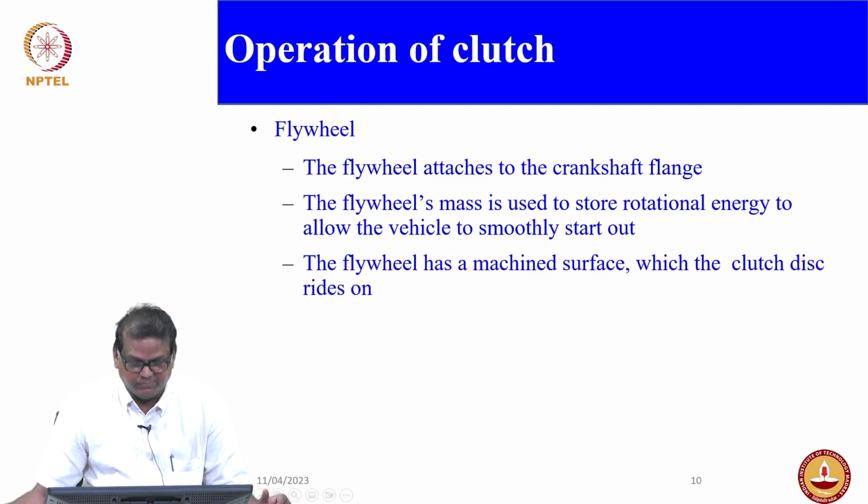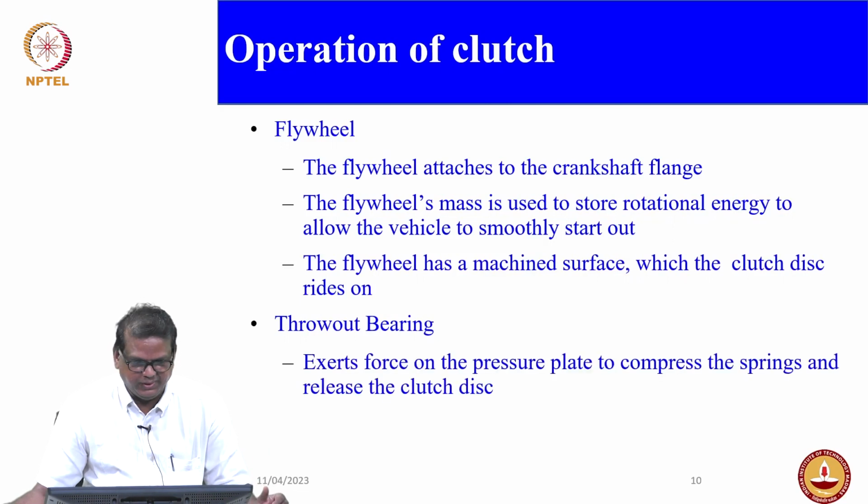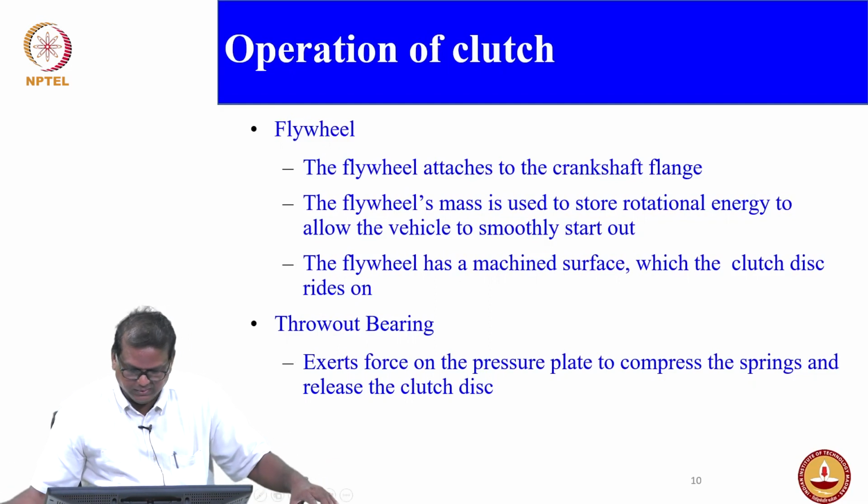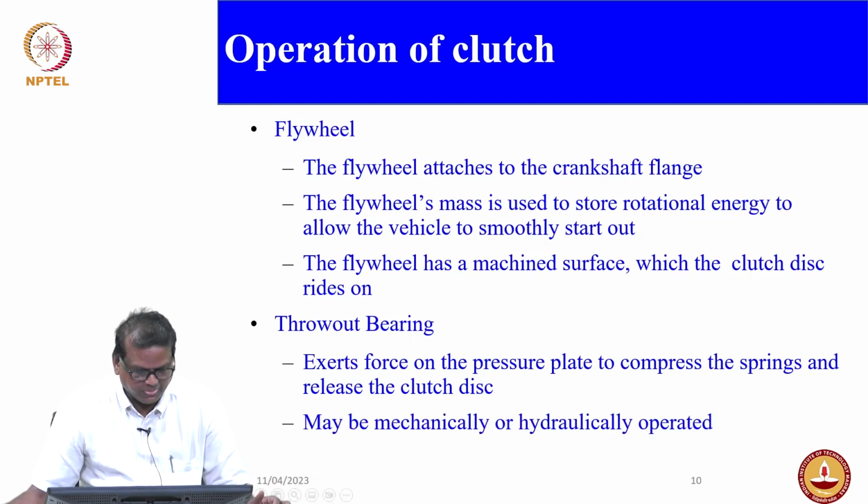The flywheel has a machined surface on which the clutch disc rides, and the throwout bearing, another important component, exerts force on the pressure plate to compress the spring and release the clutch disc. That is the purpose of the throwout bearing: releasing the clutch plate or clutch disc.